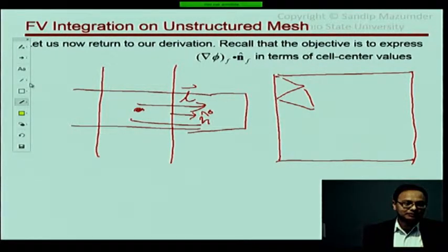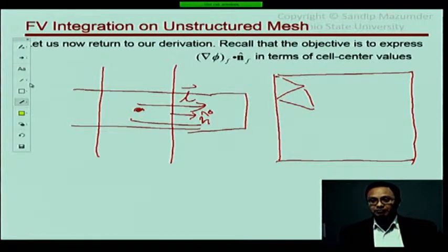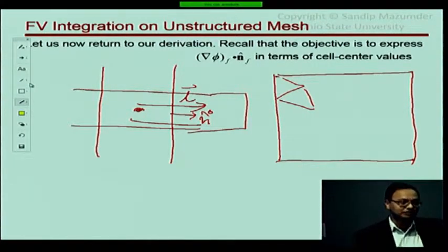Okay? So just because it's a triangular mesh doesn't mean that your normal and L vector will not be co-aligned. If they're equilateral triangles, they will be. In fact, all the great mesh generation algorithms, for example, Delaunay triangulation, want to enforce that as much as possible: make triangles with 60-degree angles all the time. Okay. Same thing in 3D.